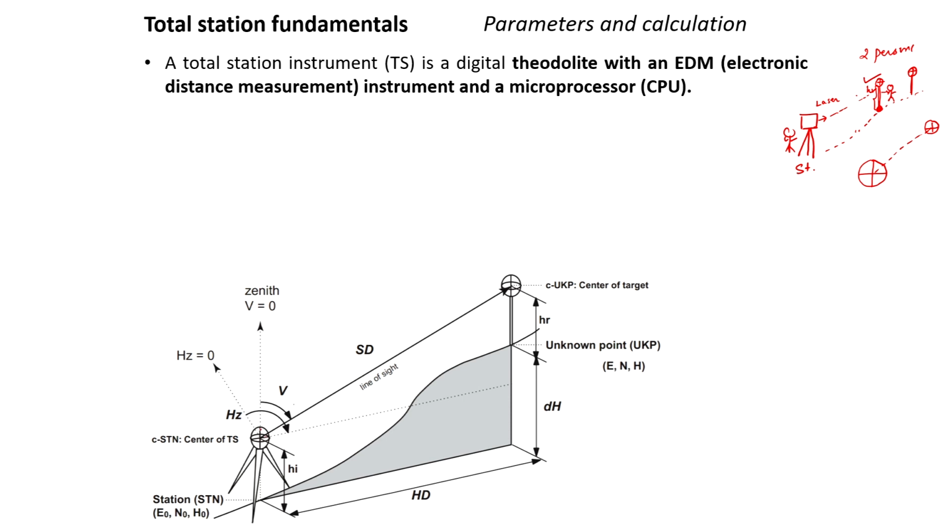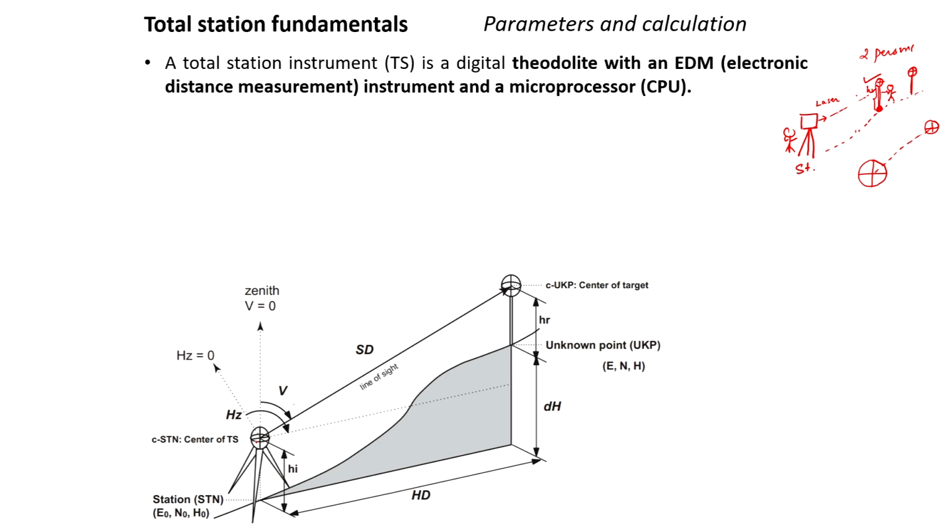So this is one important part while setting the station. Of course, you have to level the 3 legs. You have to level it to horizontal, and then fix your total station on the top of this. At the same time you have to fix the height, depending on how much obstacle there is in the surrounding area. You cannot go for 10 meters height and all that. Maximum you can put 2 to 2.5 meters or 3 meters, but mostly we confine ourselves to 2 meters of height. This also depends upon the height of the person who sets up this total station. So these are some trivial points, but very important, because they may affect your overall measurements.